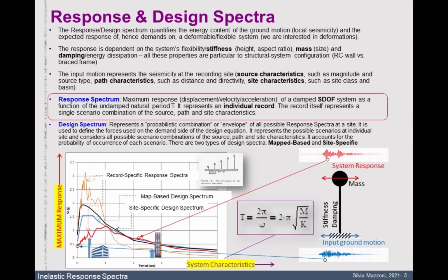As we go deeper down the rabbit hole today, keep in mind that sometimes even this simple elastic response spectrum provides 97% of the insight. So what we're trying to do is ask what additional insight we can get into our model. A response spectrum is typically associated with a ground motion itself, while a design spectrum is associated with the site and what's expected in shaking in your structure. It's very important to keep the two concepts separate, and we're going to mainly be focusing on the response spectrum.